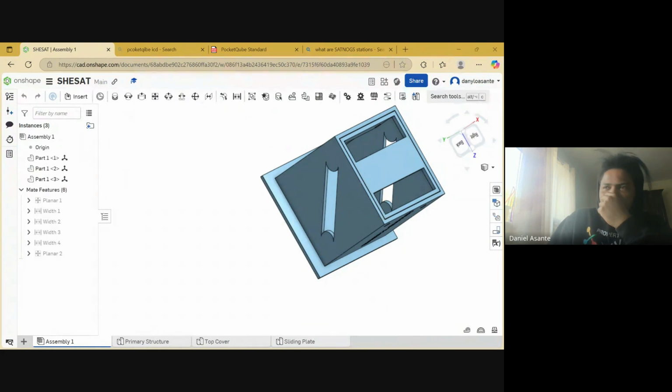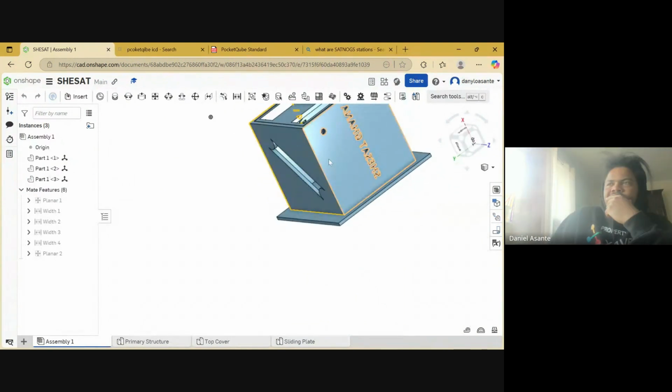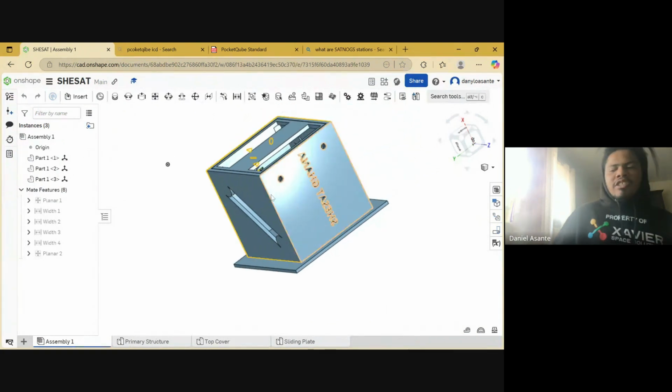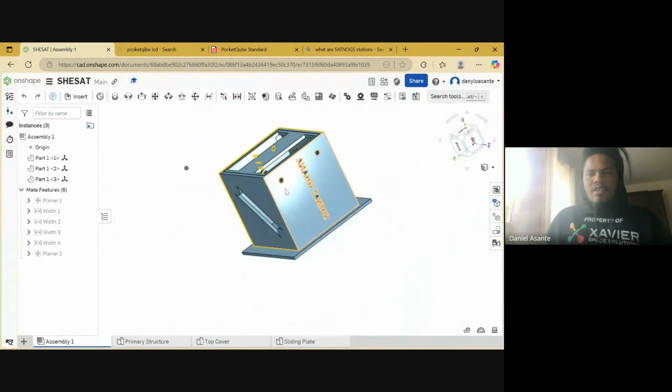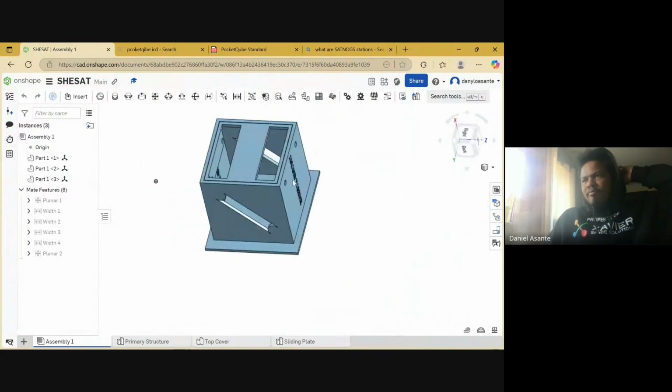Thanks. So essentially, when you build this, you can easily export it as a STEP file, and then you do the usual process. You can slice it in a slicer, and then put it in your 3D printer to print, and then you can actually have this model physically. I would hope that if we finish with this, those who can do it can watch the recording after and maybe do it, and probably I post it on LinkedIn and tag us, so you can see your pocket cube structures.